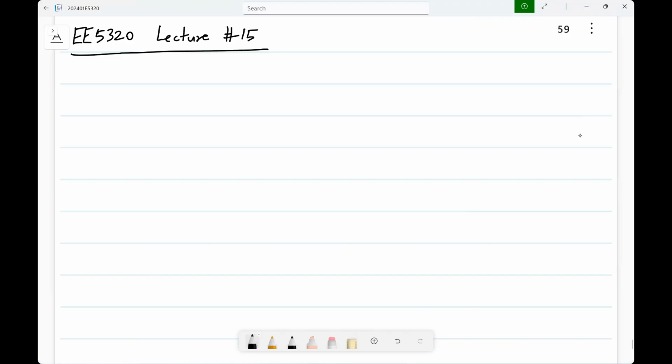done on ICs. So now we can start with any circuit, but I would say sort of the most important analog circuit, the workhorse of analog ICs, is the negative feedback circuit, right? Lots of things are done using negative feedback, like amplifiers and so on. And you also use negative feedback just for biasing transistors and things like that. So if you take any analog IC, there will be a system with negative feedback in it, and that may be using op amps with negative feedback around each op amp. And inside each op amp, there are bias circuits with negative feedback around them and so on.